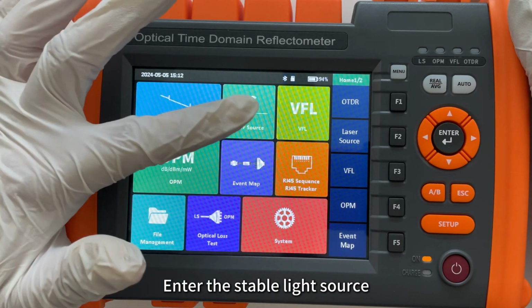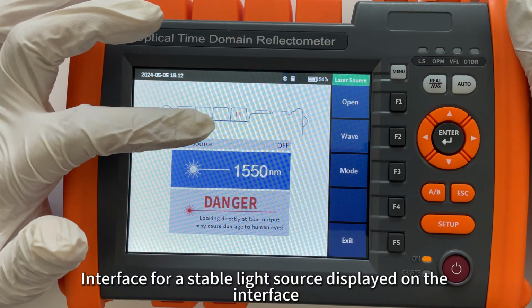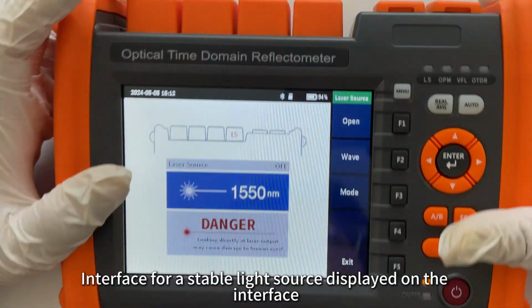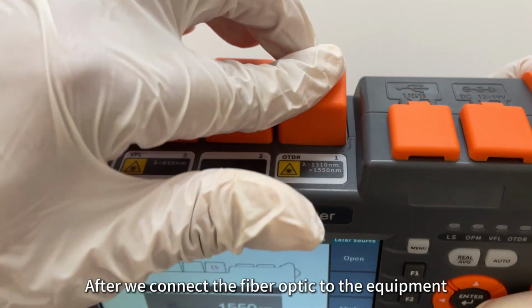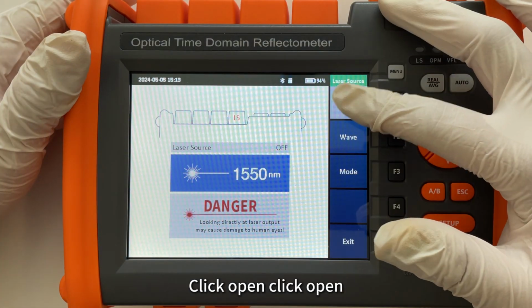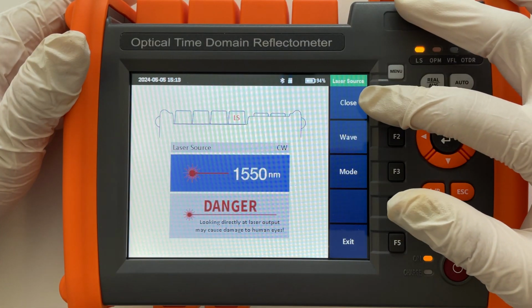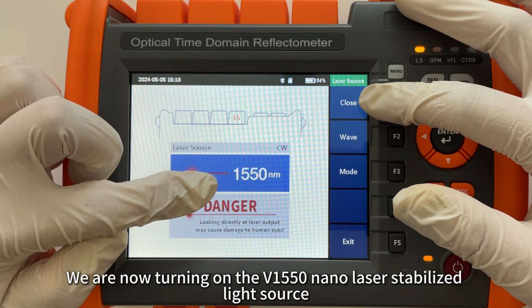Enter the stable light source. We can see the interface for the stable light source, also similar to our OTDR interface. After we connect the fiber optic to the equipment, you can see the switch. Click Open. We are now turning on the 1550 nanometer laser stabilized light source.